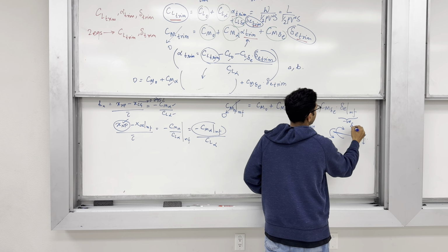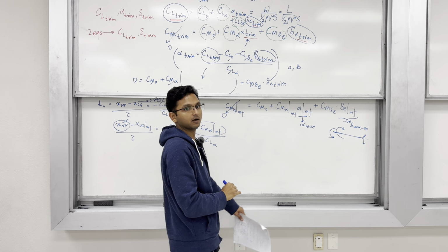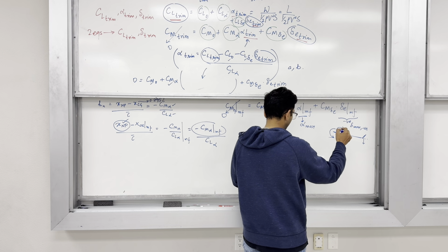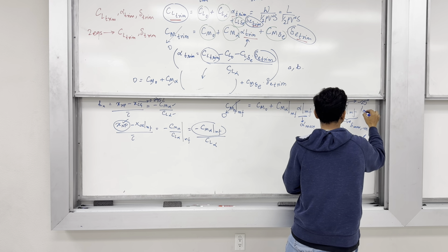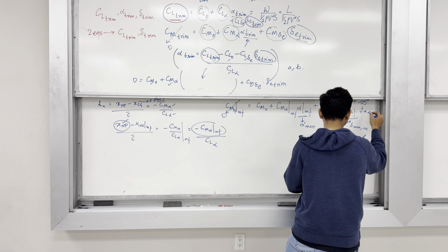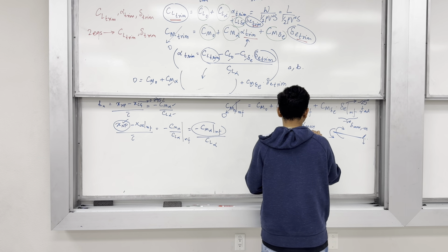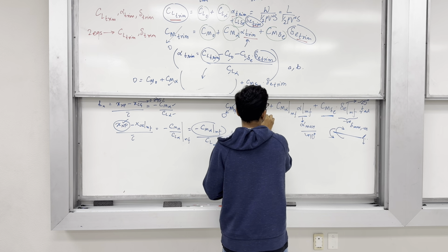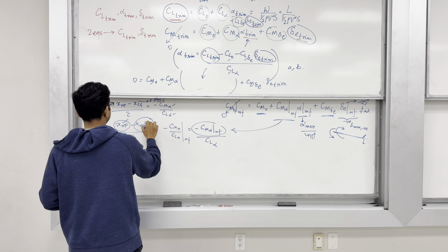And I know that upward is negative. So, maximum delta negative has to be applied, which means that I can choose this to be negative 25 degrees, and convert it to radians, because some things are in radians, some things are in degrees. So, be cautious. Again alpha max is given as 10 degrees, I am given C m delta E, I am given C m naught, I will get C m alpha most forward, I will plug that in here, which gives me x C g most forward.